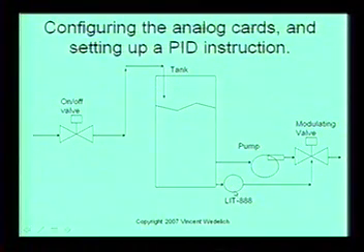Next, you have a measuring element. This is a level indicating transmitter. And usually they have a number associated with them because you might have multiple level indicating transmitters. And because this is on the bottom of the tank, it's actually a pressure transmitter. So it actually looks at the pressure of the column of the fluid. And you can study this on your own. I'm not going to go over how the physics works of that. But anyway, it's a level indicating transmitter that sends you a 4 to 20 milliamp signal back to an analog input card.